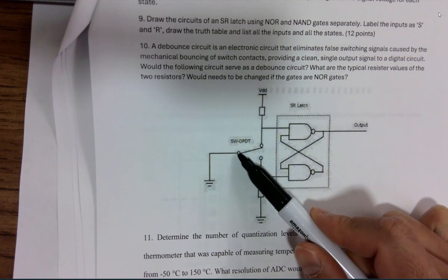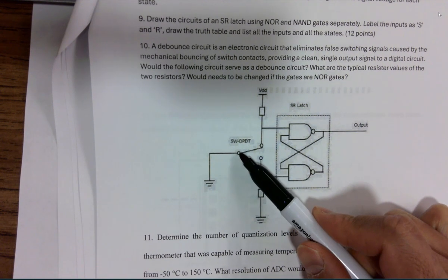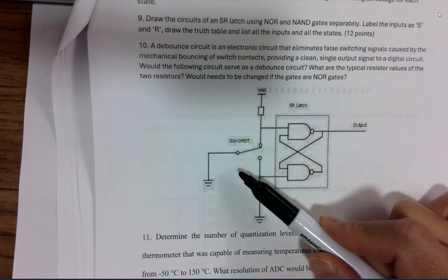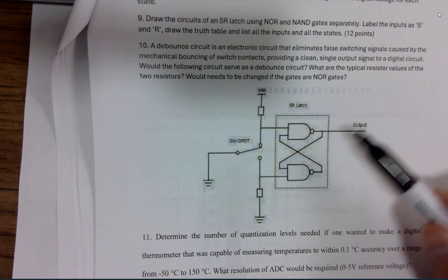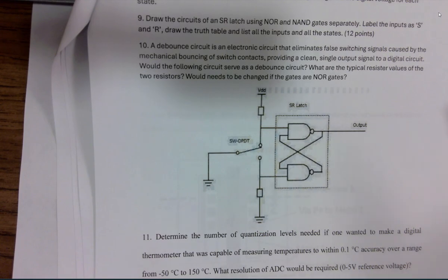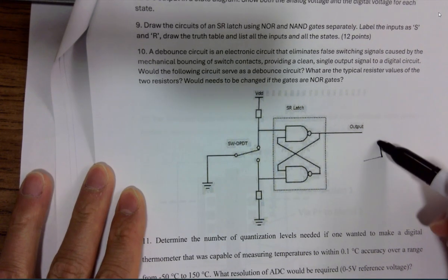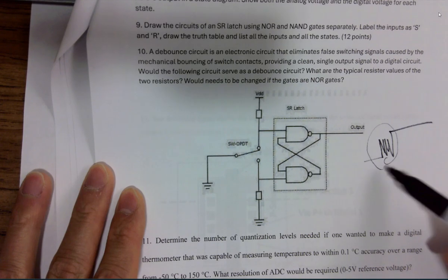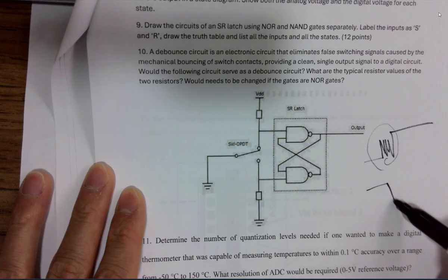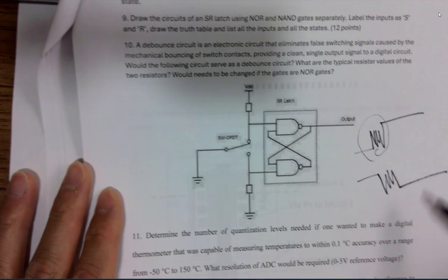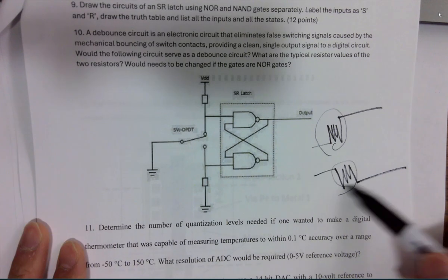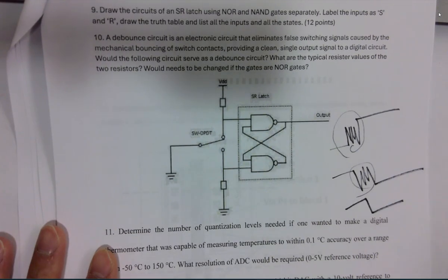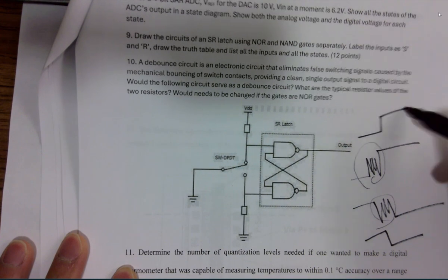So if you want to give a 1 from the switch, you should receive a 1. If you want to give a 0, you should receive a solid 0, right? Without bouncing back and forth, to get rid of this part. If you are switching to 0 and you don't debounce it, it's going to show this, right? If you debounce it, it's going to be a very clear 0 or a very clear 1, like this.